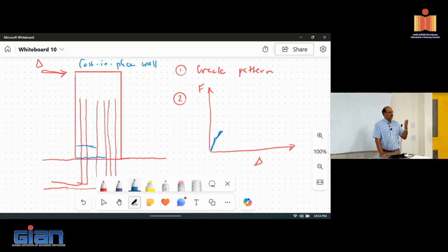Once the crack develops, there will be strain incompatibility, same as what we discussed for strain penetration, right? Then strain compatibility comes in, and you start to see the flexural cracks forming. The cracks will form depending on the stresses, so typically you will find the spacing to be roughly the same, because it is the same rebar and same concrete going through the same behavior, and your moment keeps increasing. That means your flexural cracking moment migrates upwards, which causes further cracks.